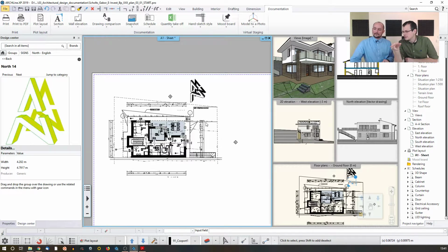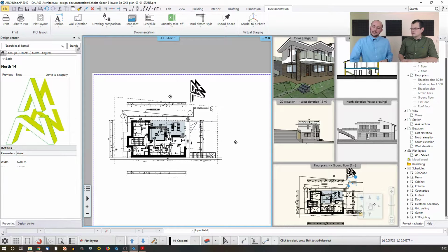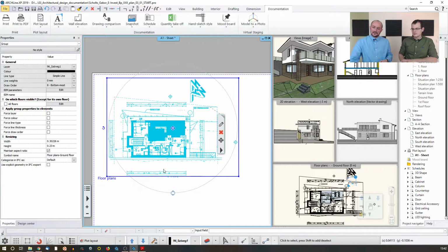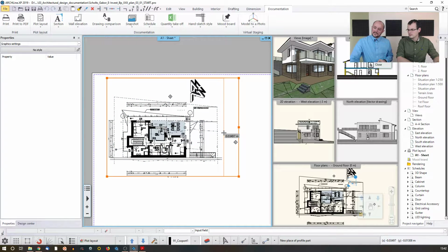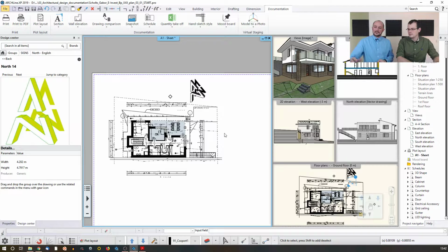Another important thing is that on the right hand side we see another elevation symbol. I don't want to modify that on the drawing, but I want to make it disappear on the layout, because I don't need that. How do I do that? Well, you can actually put it on a layer. That's also a solution, but what I'm willing to show you is that you can actually crop the contour. So when you select this virtual view of that original content, you can just click on the edge and say that I would like to offset that, and I just keep that part.